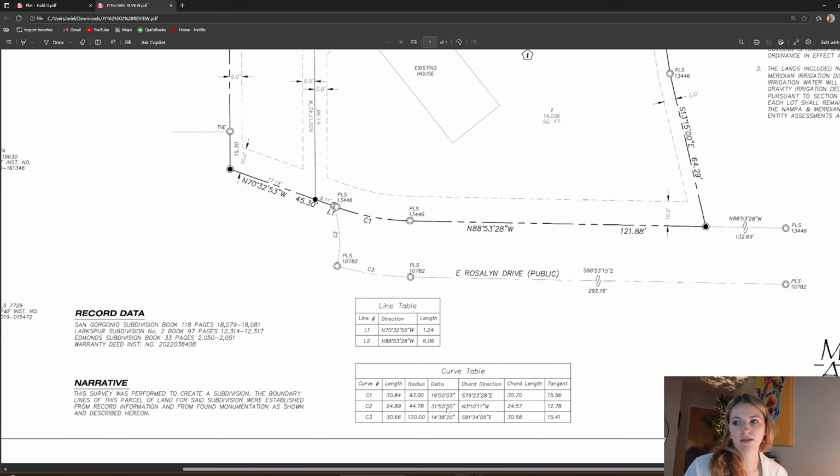I could talk about this forever and still probably get something wrong because it's a little confusing. But again, use your tools. So just import it into Chief, triple check that after you've put about 3 or 4 data points that they're all matching up still, and then you visually look at it. I normally leave my curves for last, and I will import it somewhere down lower, and then I will point to point move it to where it's supposed to be.